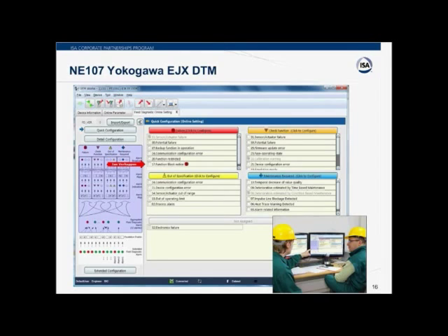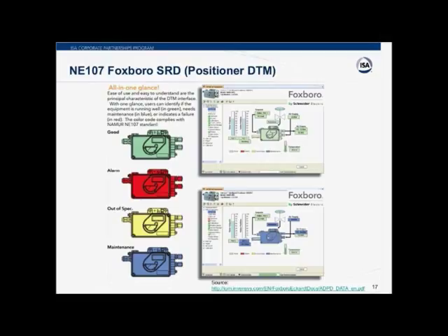So you can see if it's out of specification because of, as I indicated, an out of operating limit, or there's a process alarm or some similar alarm. So right away, when you're going to troubleshoot that problem, you know what to expect when you go out to look at the problem. Similarly, Foxboro have this with their positioners.